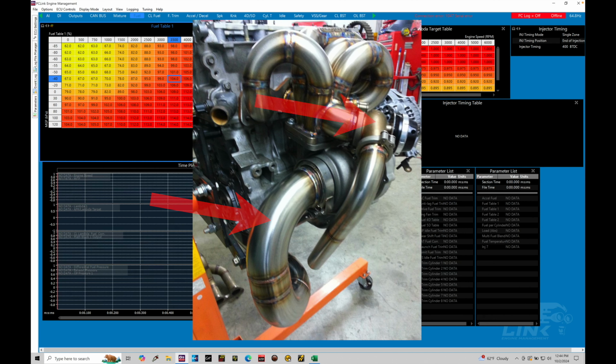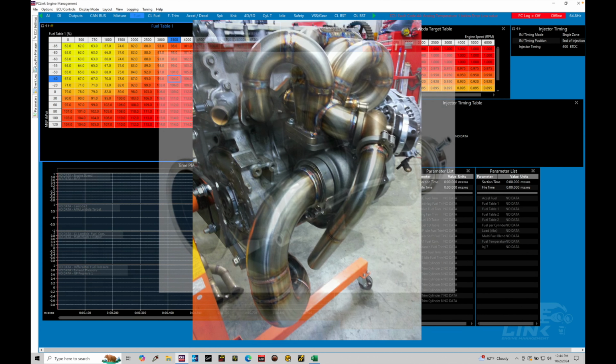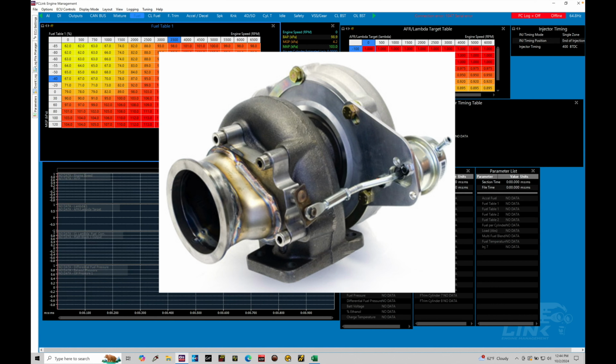We also have in this picture an external wastegate. We'll be talking about internal, external wastegates here in just a few seconds. But we'll find that this is going to be typically what you can expect for components within the exhaust system on a turbocharged engine. Now, let's start to expand on this a little bit. Let's talk about internal versus external wastegates, because what we're controlling when we're talking about boost control is controlling either an internal or an external wastegate.